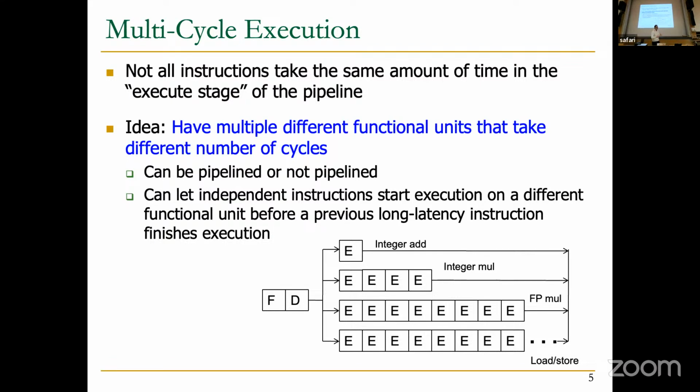Well, that was the question Mohammed asked last time. And that's the question over here, basically. How do you arbitrate the writing of the results to the register file so that you actually preserve the semantics of the von Neumann model, which is really sequential instruction processing, right? So based on what we've discussed with the von Neumann model, you should not let a younger instruction write its result into the register file or memory, because otherwise you would be breaking the sequential instruction semantics.